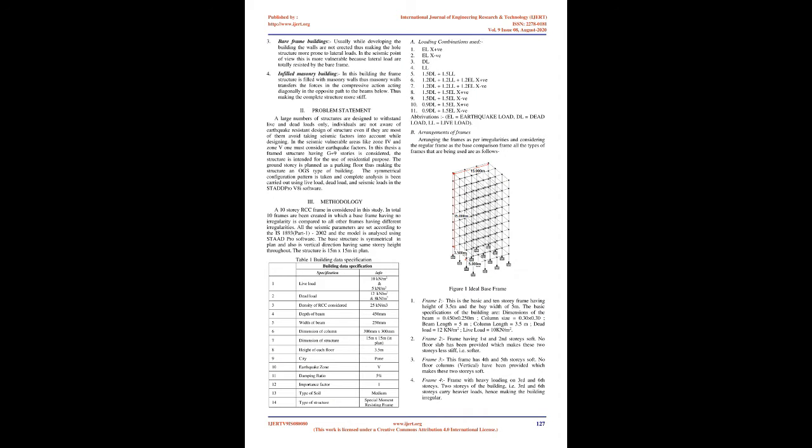At the time of an earthquake, the failure starts at the weak spot of the structure, and the weak zone in the structure lies where the mass, geometry, stiffness, etc. change. The irregularities in a structure also arise due to unexpected change in strength at a specific floor in the structure. Even for an experienced and intelligent structural engineer, it is a difficult task to avoid such conditions. Hence the focus of the existing study is assessing the relative performances of typical vertically irregular structures in a probabilistic domain.